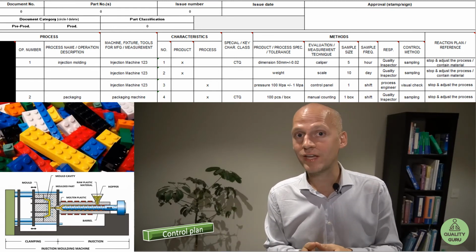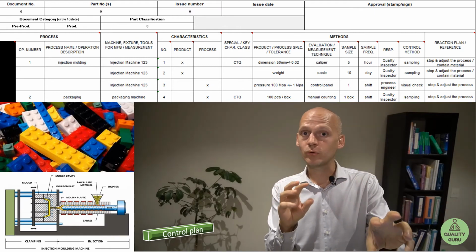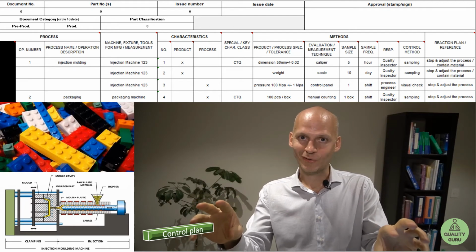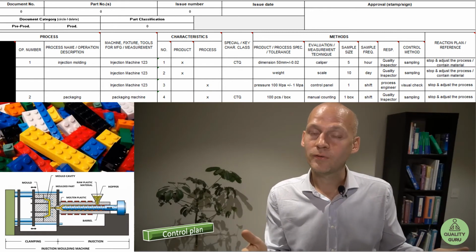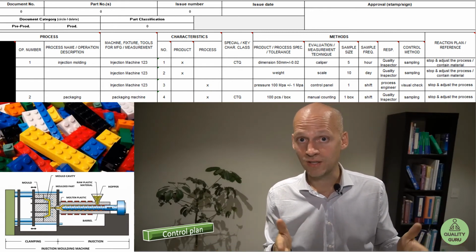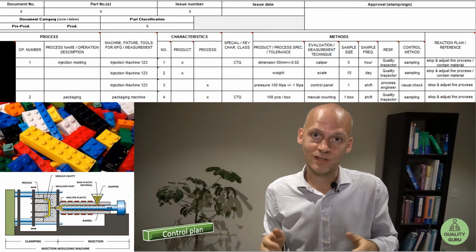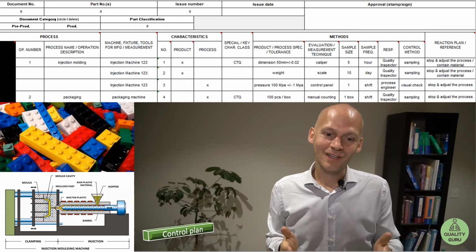And I should also contain the material, because if I have a good result one hour, a good result the next hour, but then one hour later a not good result, so the parts are rejected, then I need to go backwards and check all the parts to see if there is a problem and when the problem started, and take all the parts out of the process which are not qualified for my customer. So here, this is the basic logic.